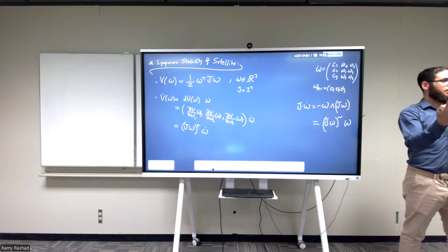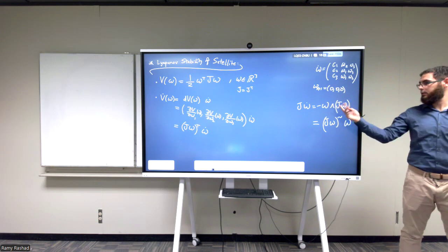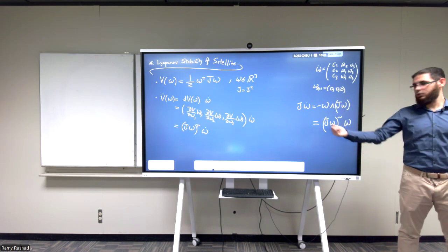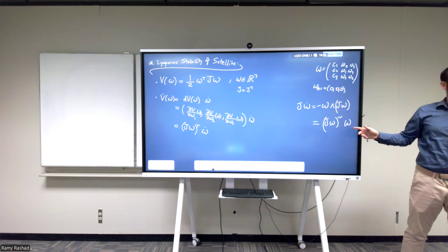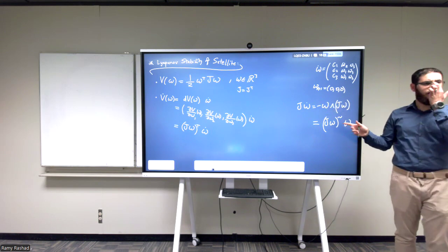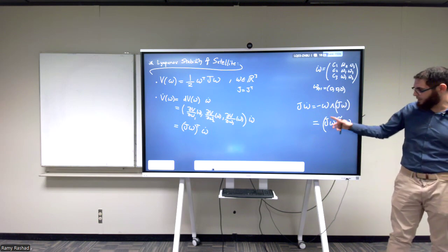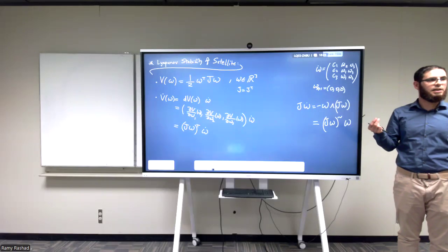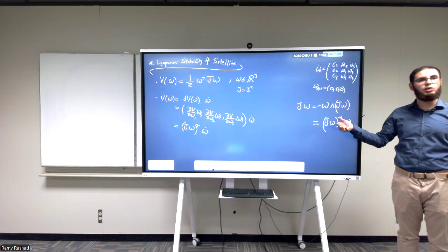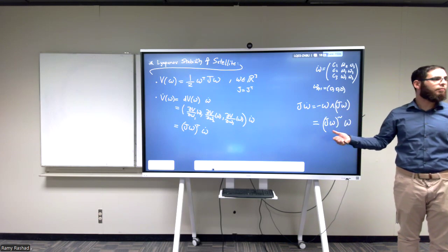And I can invert the signs. I can invert the order of the vector product, and then I can make this into a skew symmetric. So this is why J omega dot is equal to this. And if you go back to one of the previous slides, what is the J omega equal to? What is physically? What does it represent? Angular momentum, exactly. So this is just a skew symmetric form of the angular momentum covector.